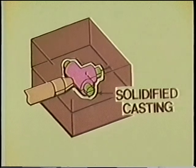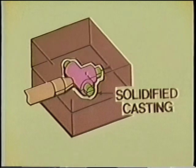Most metals decrease in volume when they go from a liquid to a solid state. They also contract when cooled to room temperature. Consequently, the initial mold cavity must be larger than the final desired shape by what can be called a shrink factor, or a pattern maker's allowance. In the case of investment casting, an appropriate shrinkage factor would be about 2%.